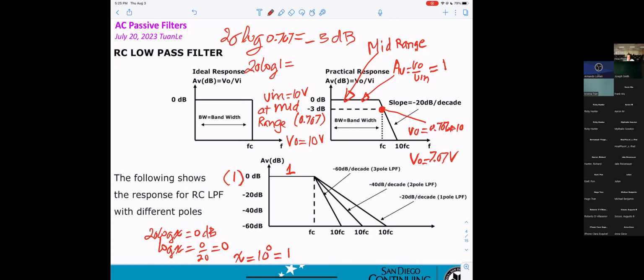Again, I already told you, you cannot do anything with the decibel. In order to know, you have to convert it into numerical values. Normally, you're working in RF, radio frequency, and it is measured in dB or dBm. However, we have to deal with watts, milliwatts, and kilowatts, so that's why you have to know how to convert it.